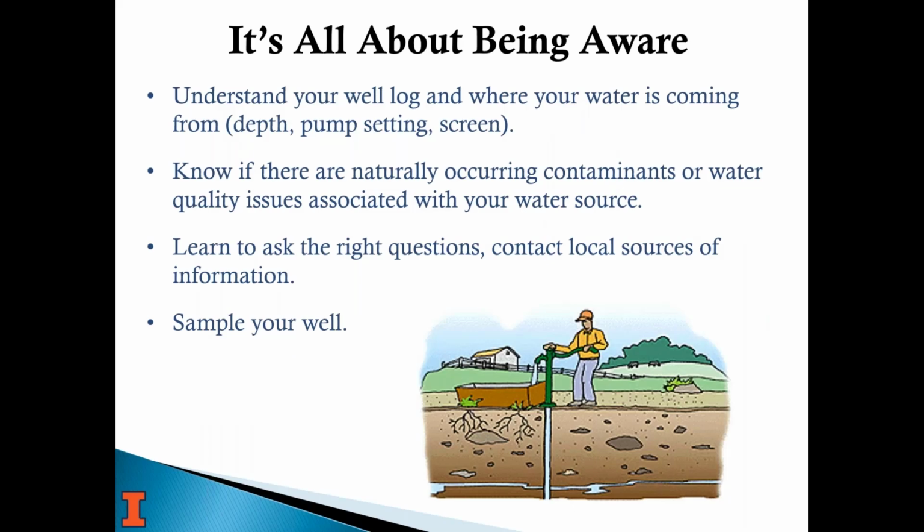So what we recommend is, if you have a well log or you can find your well log, you need to understand what it means: where your water is coming from, how deep it is to the aquifer. Most logs have a geologic list on them as you go down into the ground. Where your pump's at and why. Do you have a screen or not? We're going to talk about more of that in a minute.